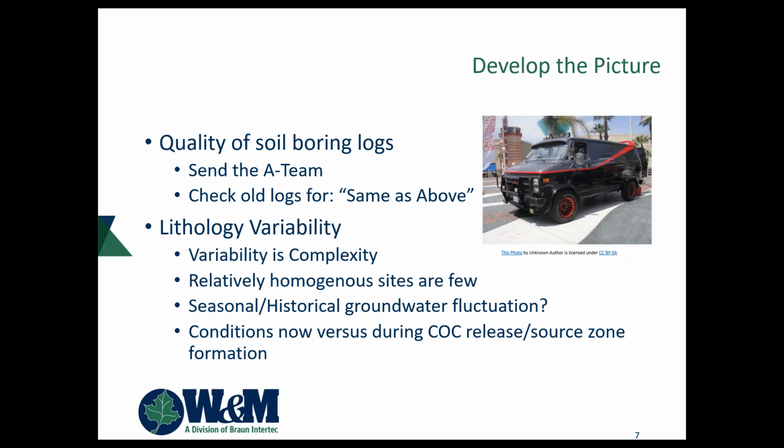That goes into variability in lithology. So what does your soil profile look like vertically, and then from area to area on the site? Because the more variation there is in soil types on a given site, the more complexity you're picking up, and generally that complexity can lead towards dramatically increased cost.